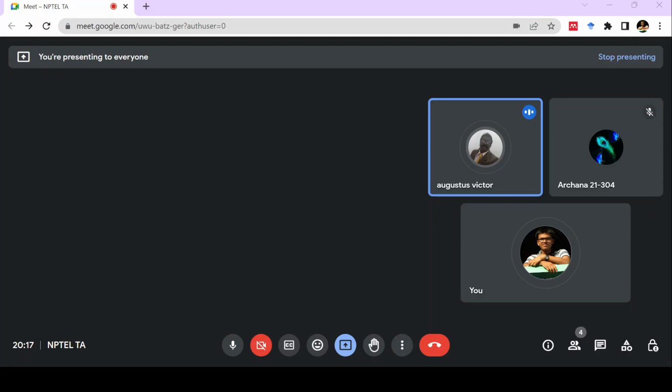This is equal to minus Fx. So this Fx, which is what we needed to find out, is rho V square A times (1 minus cos theta).